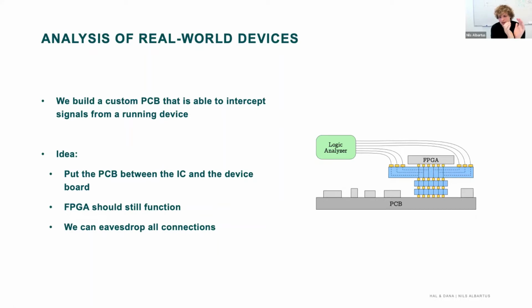And if you apply the real world inputs to your netlist in simulation, this means that everything propagates through your design, and if you even record this for a couple of seconds, you can basically in HAL then click on second 0.5 or whatever and see what value each net has at that given time, which has been great for us to understand what has been going on.